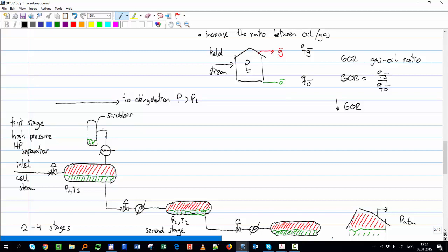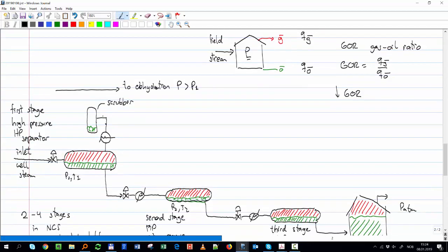But it's very similar to this one. Because it's for gas, it's vertical and much smaller. But the main purpose is to remove that additional liquid from the gas. And after I do that, I can be sure that whatever is coming into that compressor is relatively dry, no liquid. So I cool down to remove even more liquid, knock out that liquid, and then I simply connect it here.